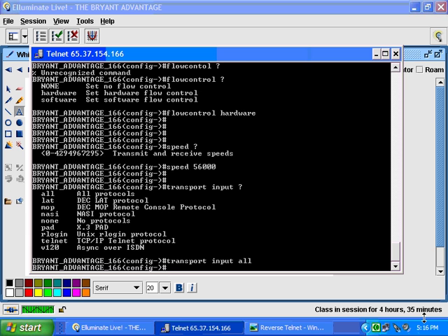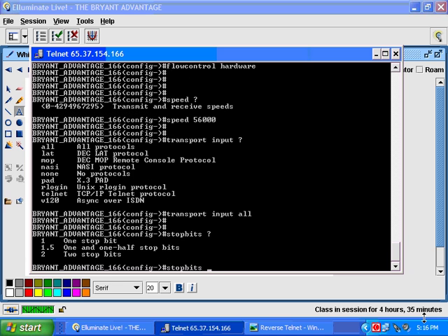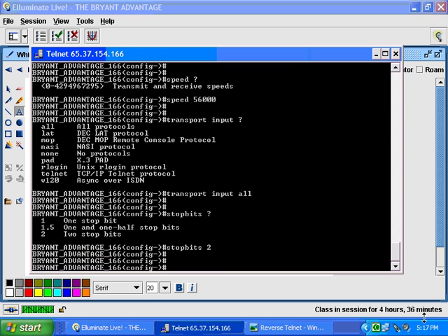Now, when it comes to the stop bits, those of you who use HyperTerminal a lot are certainly familiar with having to set this as well. Different modem manufacturers will dictate different numbers of stop bits. And you shouldn't just put 1 because it sounds good. You should check that documentation. We're going to put 2 here. It's a good idea to know the choices there: 1, 1.5, and 2. Why we need 1.5 in there, I don't know. Probably just the modem manufacturers being hard-headed.